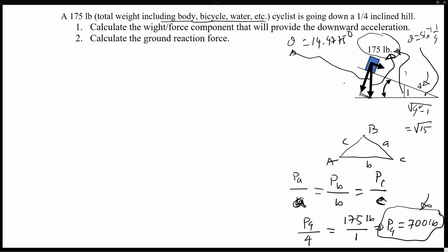Now if you resolve in the direction of theta, it's going to be 175 cosine 14.4775 degrees, which is 169.44 pounds.